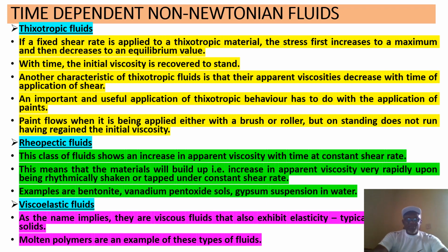An important application is in paint. Paint flows when it is being applied, either with a brush or roller, but on standing, it does not flow again; it sticks. Now, the second time-dependent non-Newtonian fluids are rheopectic fluids.